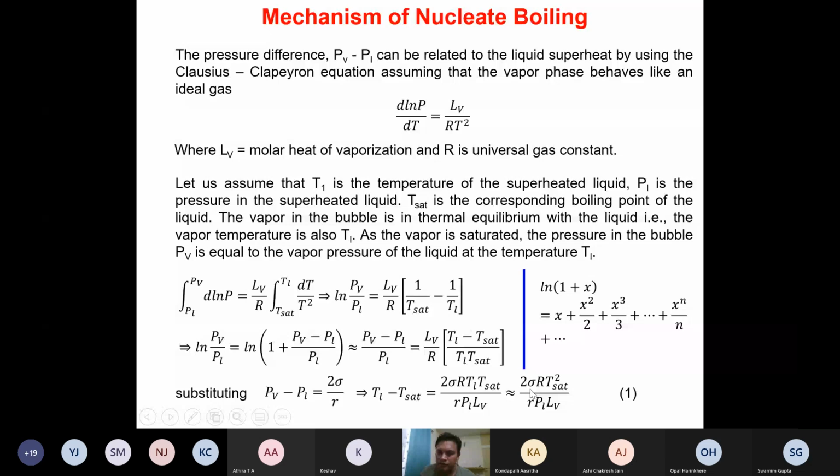So everything is more or less known, and based on that, if you want a particular size of stable bubble, we can calculate how much degree of superheat above the saturation temperature is required using this. Again, the prediction by this equation is slightly an over prediction, in the sense that stable bubbles form even at a lower value of superheat, because this particular equation is for homogeneous nucleation. That means nucleation takes place only in the liquid. That is what has been assumed here.